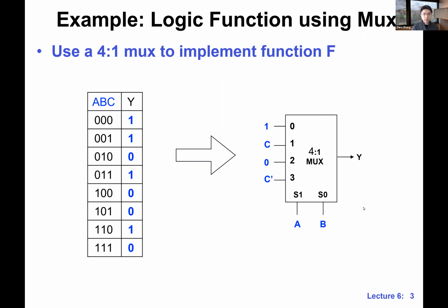Of course, that's combinational logic. This is the quiz, and I think most of you did very well. The interesting part is these two inputs. If you look at this input, this is input 1. We're looking at these 2 rows, where A, B are 0, 1. We check the C input and the Y output, and in this case they agree, so they are consistent. That's why we just set Y to be C.